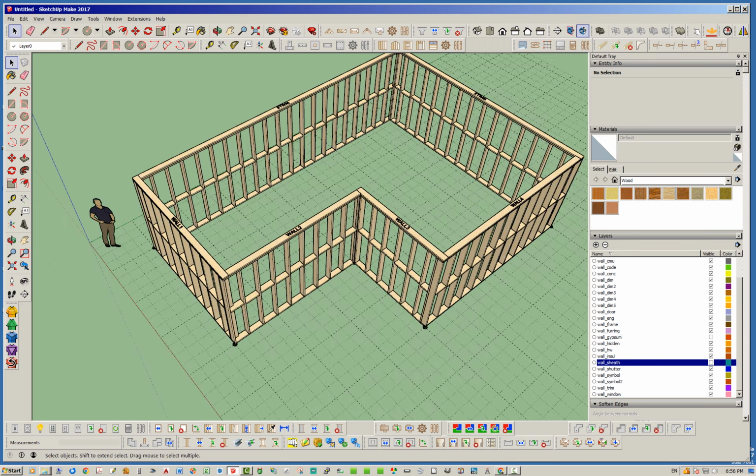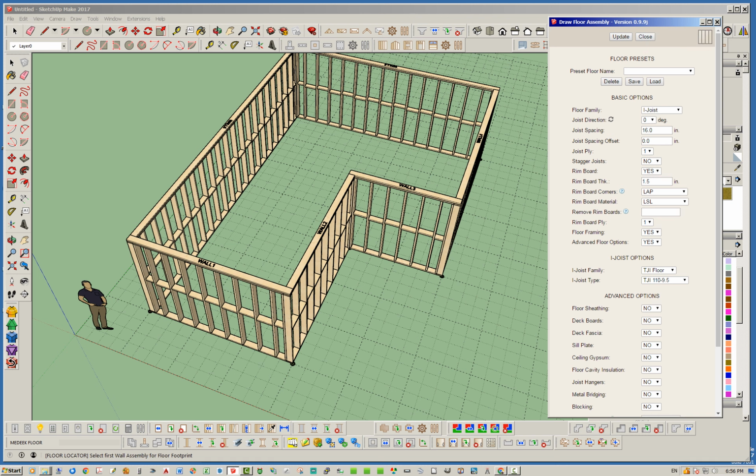So now, let's use the draw floor tool right here. Give it a second to load. It's got to create all those layers. Okay, so now what you can see here is we've got this little corner icon up in the top right corner, and that is typically in polyline mode. Of course, I think you can change that in the global settings. If we click that twice, it'll take us into the wall mode, or draw mode equals wall.